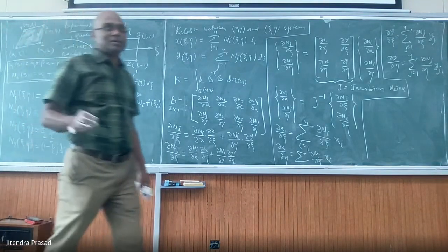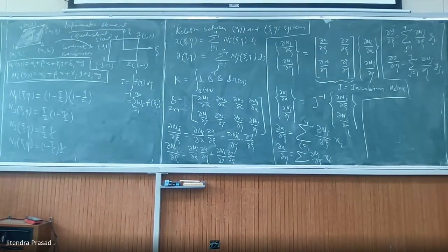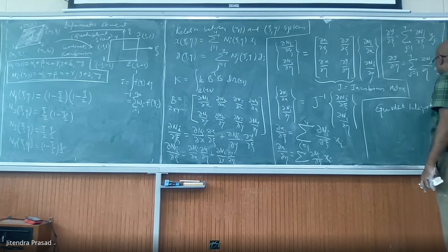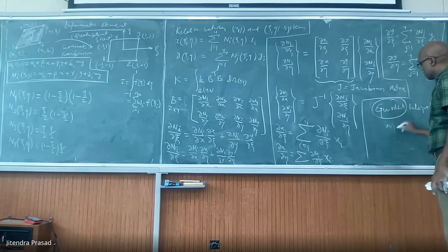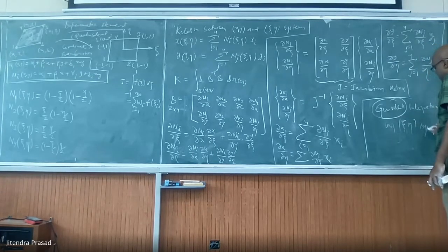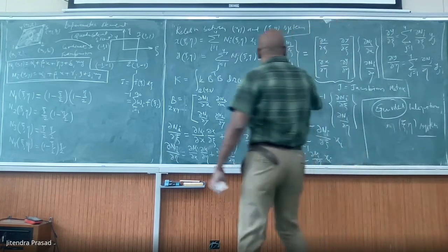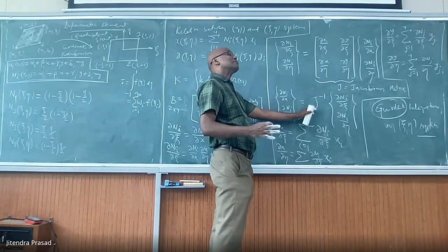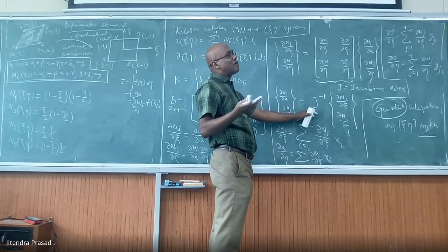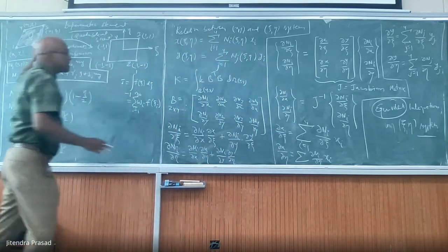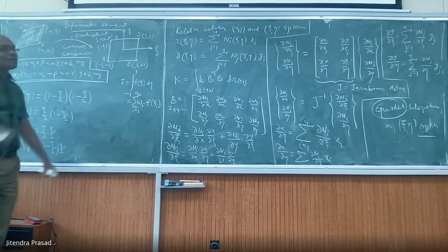Okay, that we will do tomorrow, and that will also cover how to apply Gauss quadrature in this. So equivalent integration, or rather just integration using the xi-eta system. That's what we have to learn. Otherwise, everything is covered already. So we have del n I over del x in terms of xi-eta, and we want to know how something given in the xi-eta system can be integrated in such a way that we get exactly the same value as in the x y system. That we will do tomorrow.